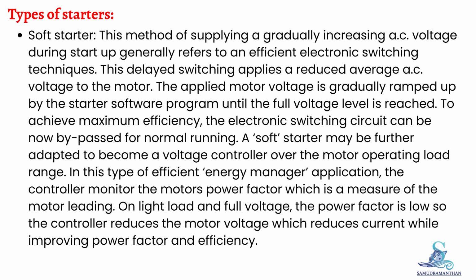A soft starter may be further adapted to become a voltage controller over the motor operating load range. In this type of efficient energy manager application, the controller monitors the motor's power factor, which is a measure of the motor loading. On light load and full voltage, the power factor is low, so the controller reduces the motor voltage, which reduces current while improving power factor and efficiency.